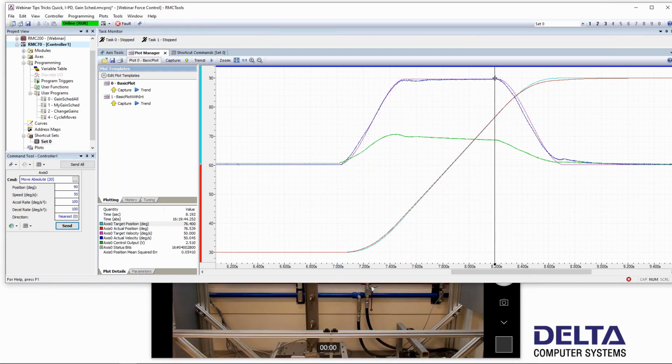So this system is a great candidate for gain scheduling. We can change the gains here versus here versus here, and hopefully that'll give us a little bit better control. You notice here that we're not following so well at the end, and my guess is because the integral gain is having problems dealing with this changing system and causing the undershoot over here.